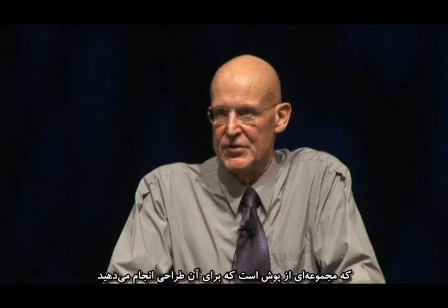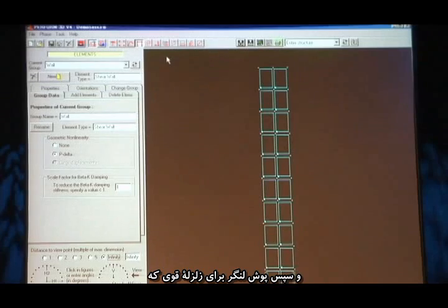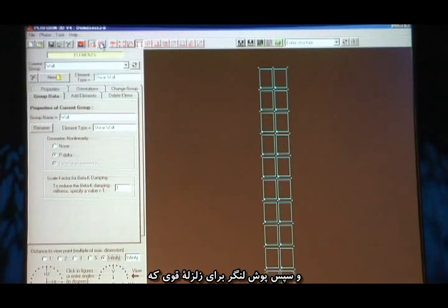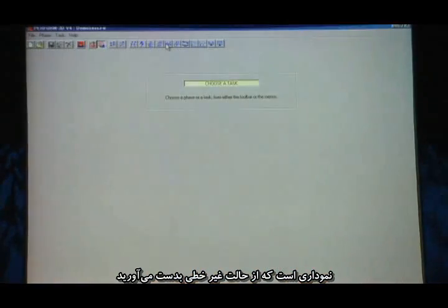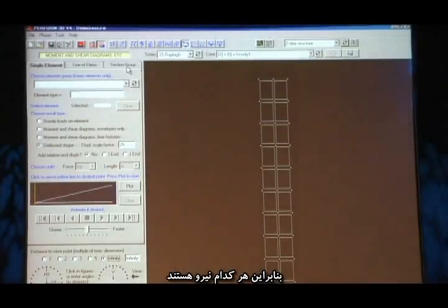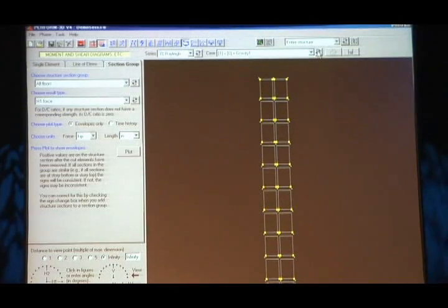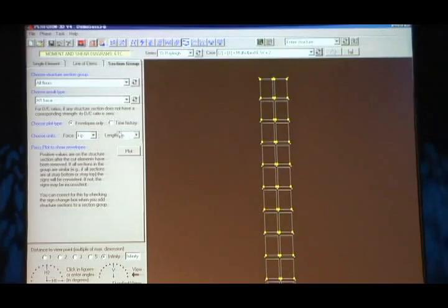And so what I'm going to have a look at is the moment envelope for the weak earthquake, which is the sort of envelope you design for, just the shape, and then the moment envelope for the strong earthquake, which is what you would get from the inelastic case. So H1 force, and I need, okay.